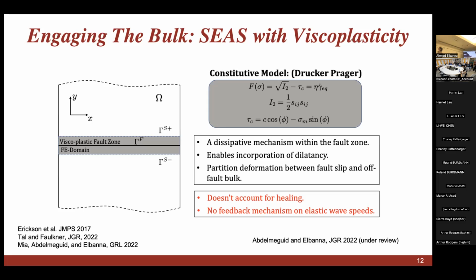The crucial part here is that the fault zone strength is dependent on the mean stress. So more compression will make your rock stronger. If you have tensile perturbation, less compression will make the fault weaker. And I look forward to debating whether this is the right description or not. It's not, because we actually don't know how faults or rocks evolve at this scale, but it's a plausible mechanism, and it's widely used in geotechnical engineering to describe inelastic behavior.